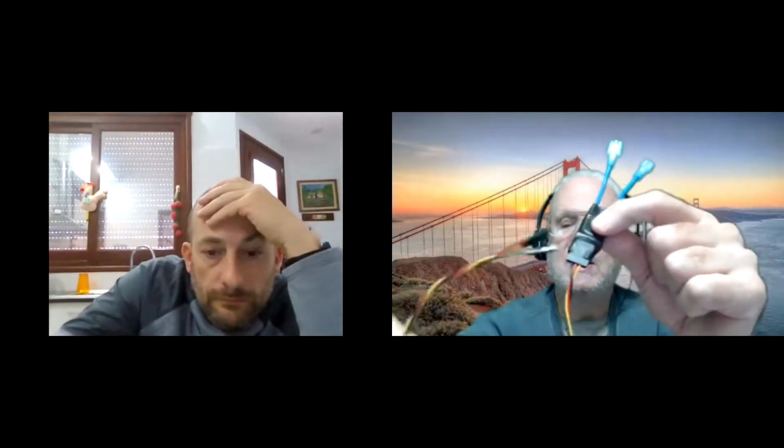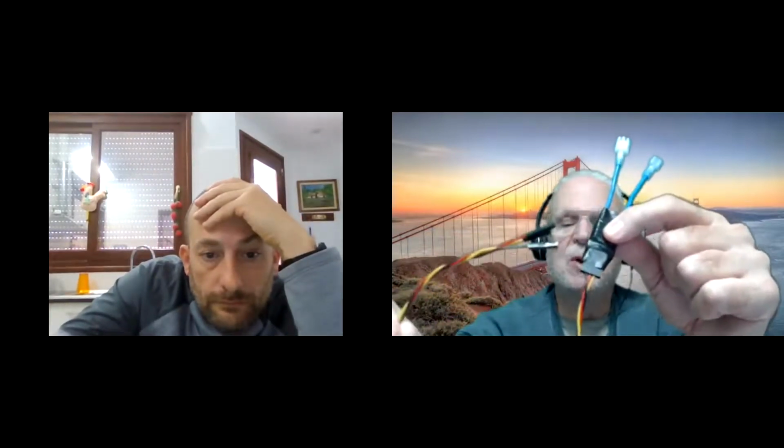They're just a little square board inside of here. It's got the two wires soldered on that I'll put in series with the motor control stuff. And then three wires go to a controller somewhere. So I put on voltage and ground, and then it puts out a voltage proportional to the current. So that will give me something else where I can now monitor the current on the motor.